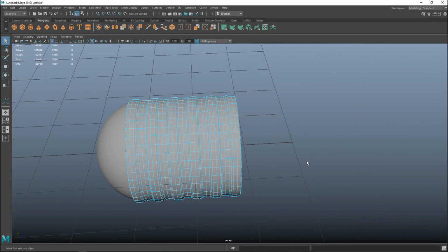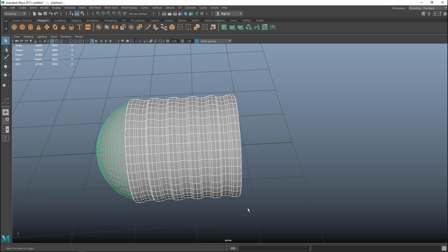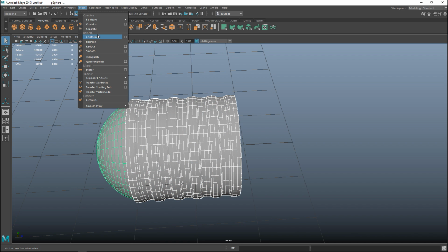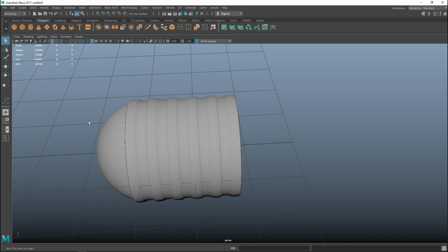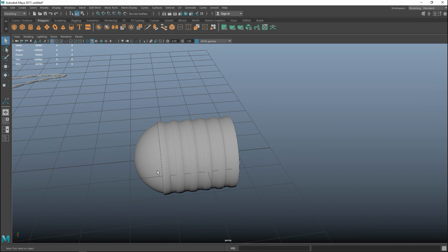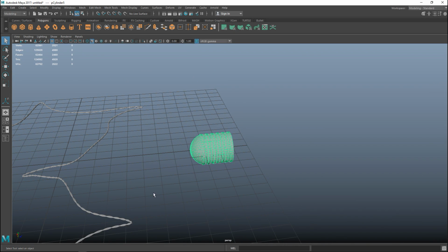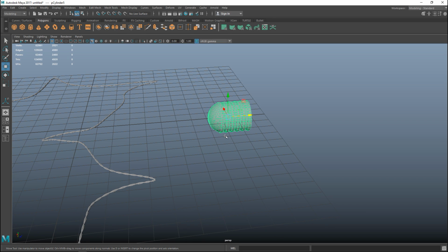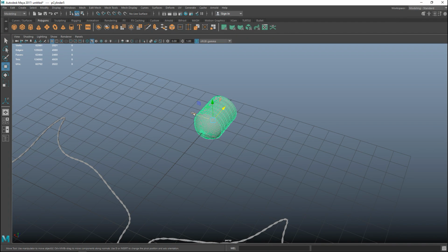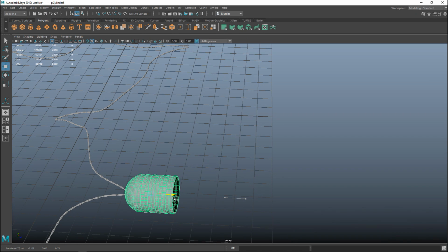Okay, cool. So what we're gonna do is we're gonna right click at object mode, we're gonna select both and go to mesh and combine. And let's just take this and kind of position it and scale it so we kind of know what size we're looking at and so forth. So I'm just gonna move that in here. It's obviously way too big, so let's bring that way, way down.